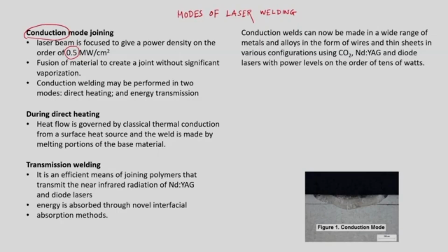Here we are applying the laser beam energy and generating significant melting without vaporization of the work parts. We deliberately apply controlled laser beam heat energy to get melting only, and by using this melting and redeposition we get shallow weld joints.